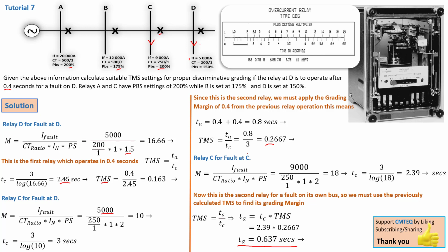It doesn't matter what's going on here. The situation here might be healthy, with nothing going on, but if something arises here, this relay cannot rely on the 0.8 actual time, but must rather have the 0.6 seconds. So that's the difference between the two actual times. I hope we are on the same page here.